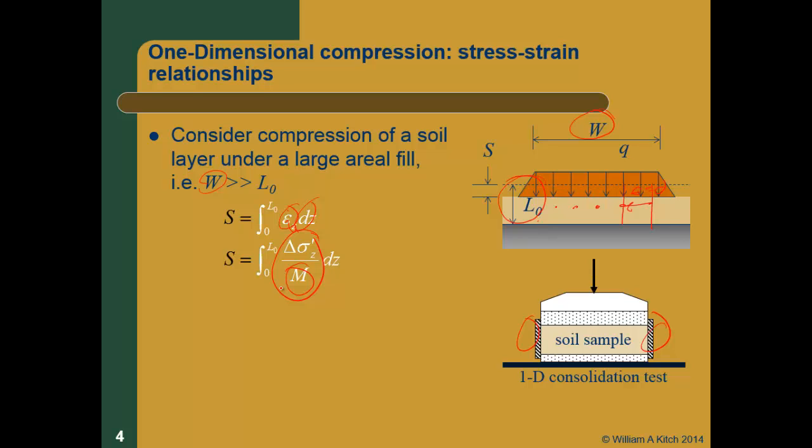This is analogous to Young's modulus, except what were the boundary conditions for Young's modulus in the horizontal direction? It was zero horizontal stress. This one is zero horizontal strain. Okay, so it's a different boundary condition, different modulus, and there is, guess what? Is there a relationship between constrained modulus M? I think that's the definition. M is the constrained modulus.